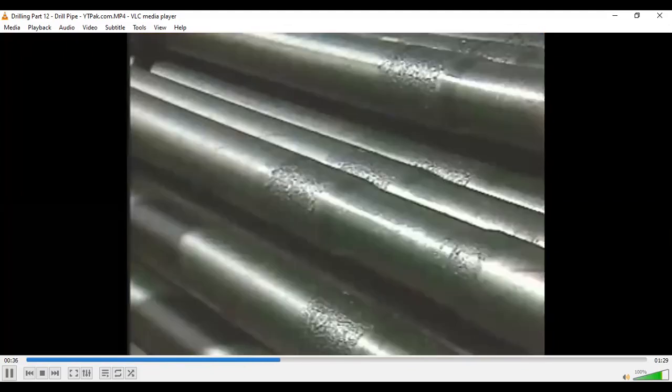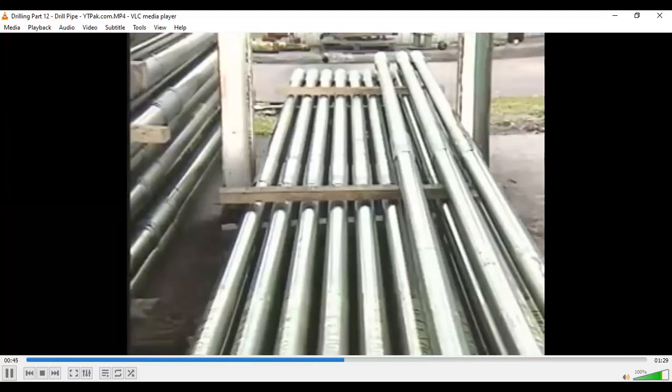The bottom hole assembly includes all of the tools below the drill pipe and above the drill bit. These tools promote drilling objectives in a number of ways. Drill collars maintain tension on the drill pipe, provide weight to the drill bit, and stabilize the bit as it turns. Heavy-walled drill pipe helps prevent drill pipe fatigue failures by providing a smooth transition between the drill pipe and the drill collars. As I said, the heavyweight drill pipes provide a smooth transition from drill pipes to drill collars, so they are used in between drill pipe and drill collars.